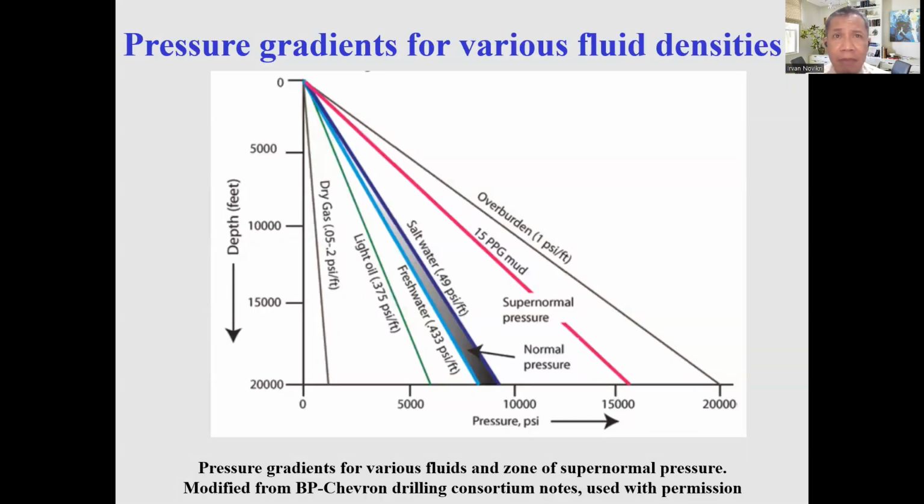In analyzing plots related to fluid pressure, an important concept is the density of the fluids. The slope of the pressure points on the graphs indicates the change in fluid density. A gas column has a lower density compared to an oil column, which is reflected in an increased slope on the graph.